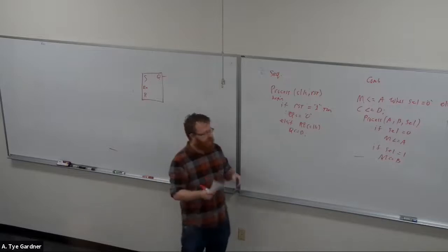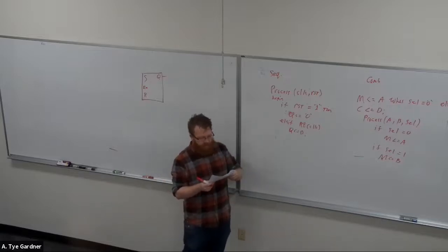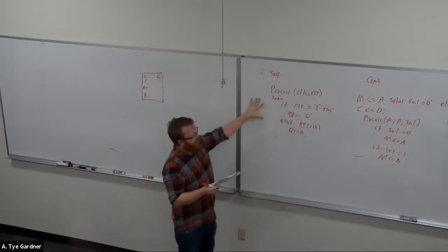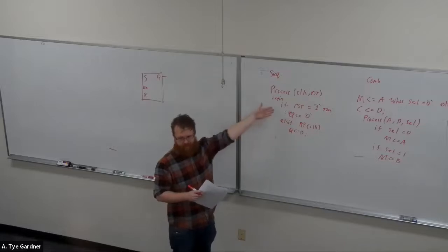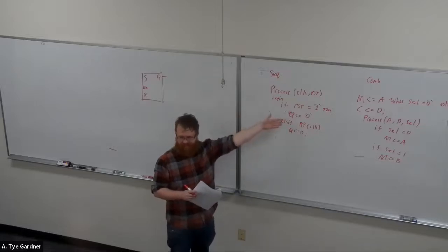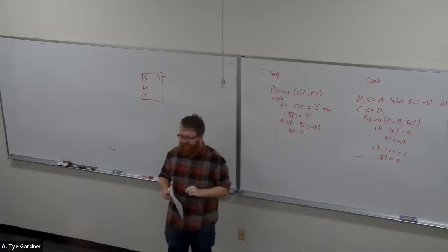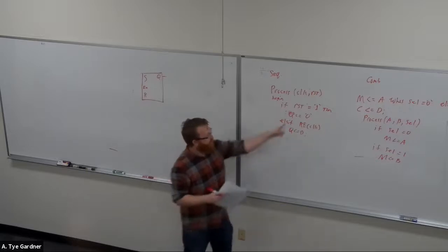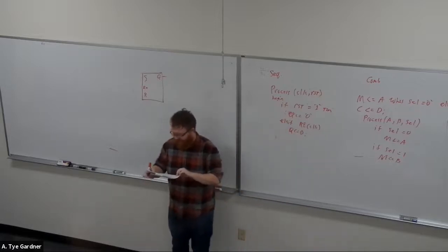Yeah, so I actually have another question in here where I give you some VHDL, and it asks the question, is this reset synchronous or asynchronous? And it is asynchronous, because synchronous means it depends on the rising edge of the clock, okay? If the reset doesn't care what happens to the clock, it's asynchronous.